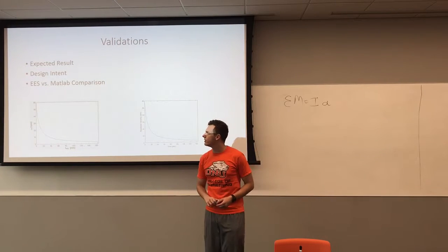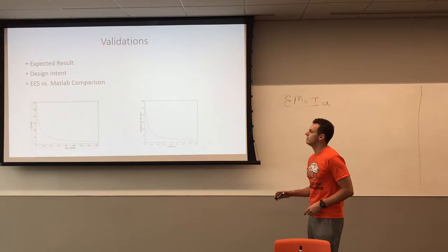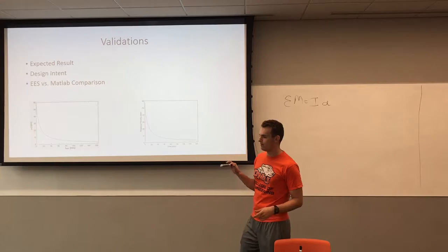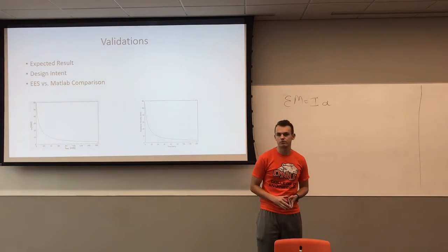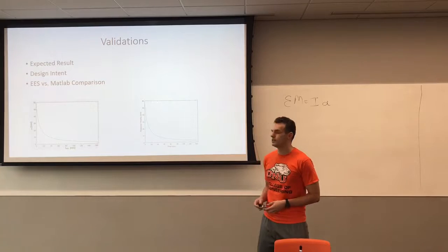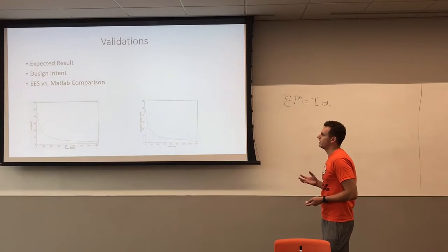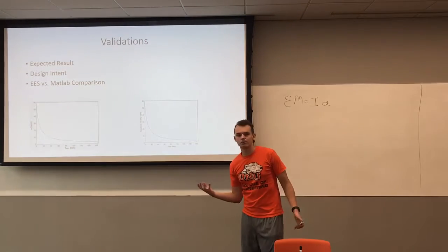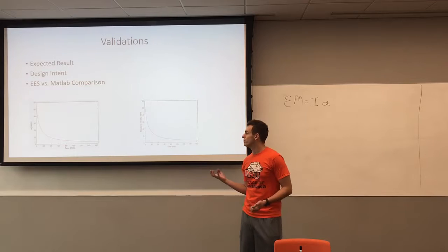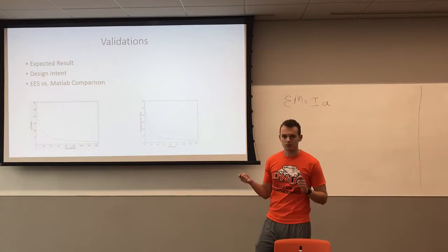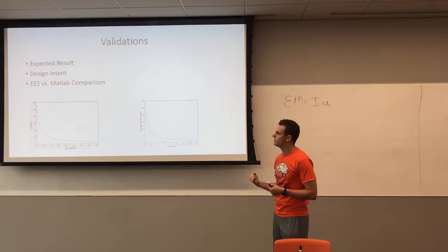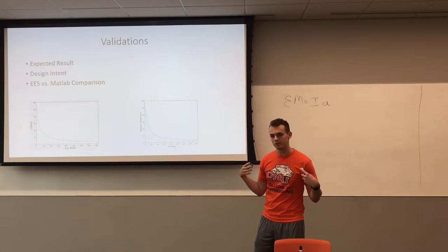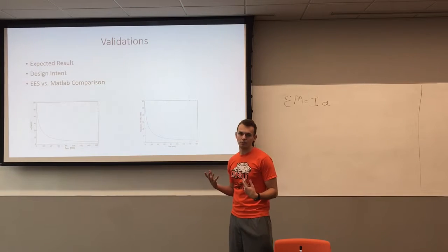The second consideration I took in validating was the design intent of why they would want it to spin for this long. I did some research online and found an article detailing autorotation, which is a phenomenon created when, if something were to happen while in flight and the motor was to shut down, to keep it from stalling the blades, they would disengage the motor from the rotor, and it would continue to spin due to the large mass moment of inertia that it possesses.